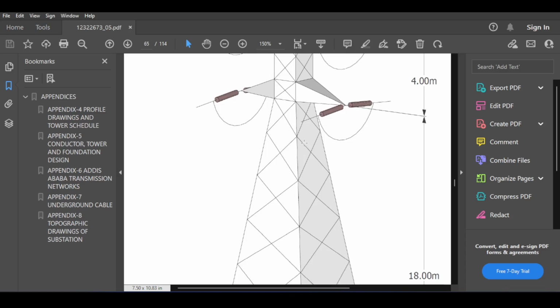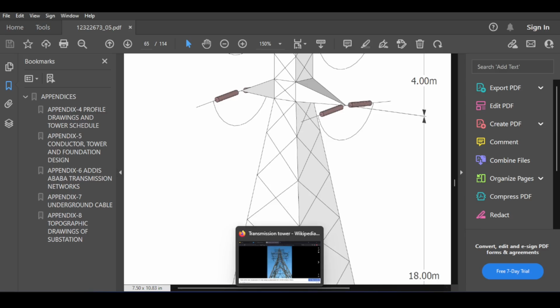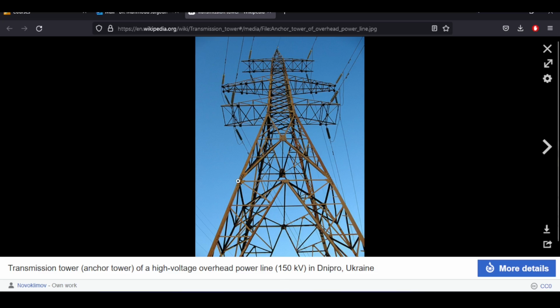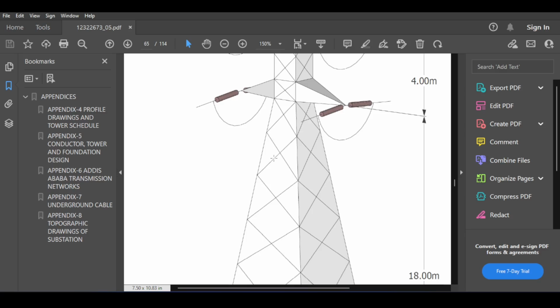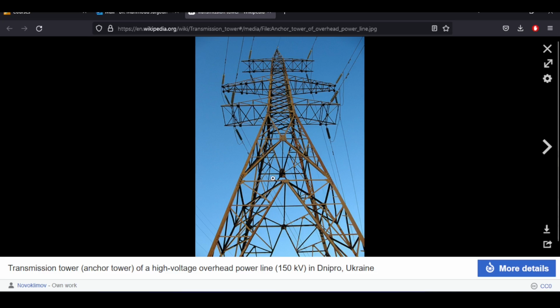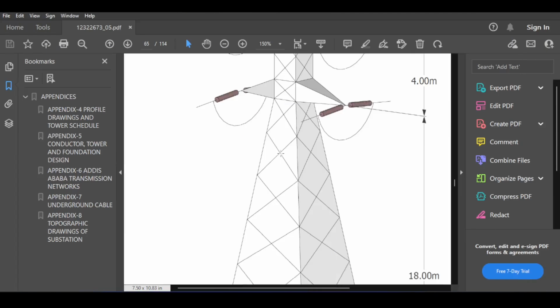And you can see that this is done as you can see in the drawing. It's just a 3D system. It seems that there are no horizontal bars, but the horizontal lines were just planes where those lines connect. Now, this is not a must. There is a gajillion ways of doing a transmission truss or lattice steel system. For example, this one incorporates horizontal members with a gusset plate in each horizontal member. But of course, it depends on what you want to do. You can assume, and this is important to notice, that here you have a connection and a gusset plate like this. And you can assume also that here you don't have a connection and you don't have a gusset plate like this.